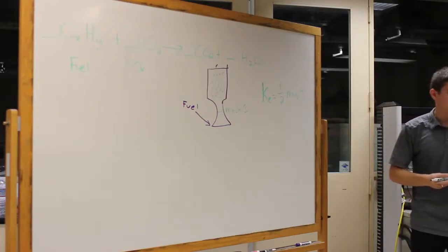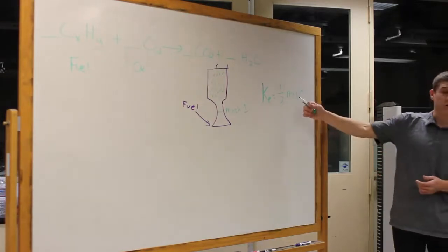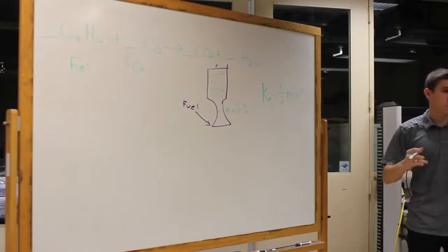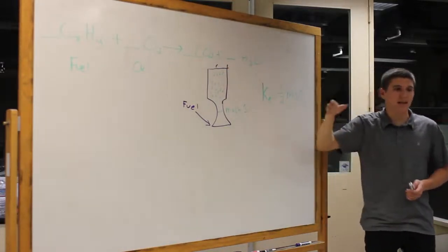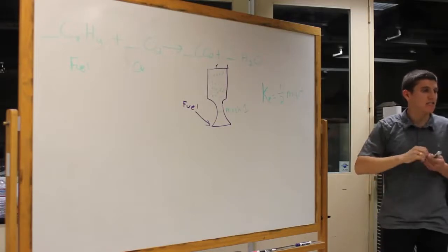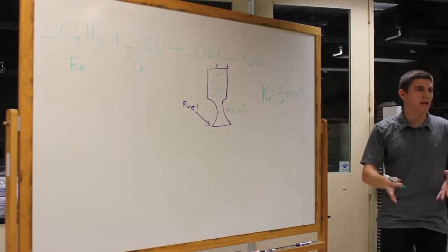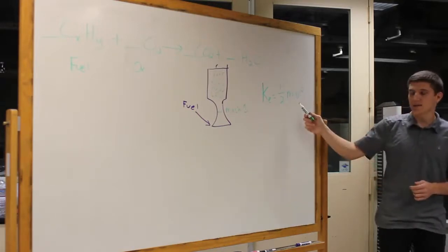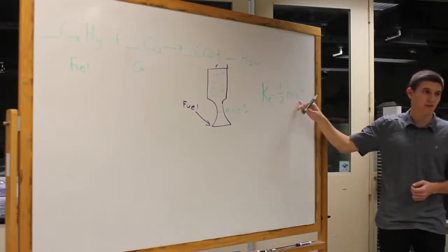So the whole idea between solids and liquids, and why liquids are more efficient, comes down to this equation right here. It's because solid rocket motors create, most of the time, solid phase combustion products. So instead of being gases up here, where they're lighter than solids, they'll create aluminum slag and stuff like that, and it'll spit out aluminum powder. That aluminum powder doesn't become gas, it's a solid, so you're spitting out hot aluminum. That hot aluminum does give you thrust, but it's not going to be nearly as efficient as liquids or gases, because they have less mass and therefore they can go faster.